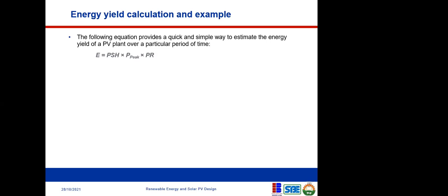That is what this means: how many hours is the sun going to be out? And like I said before, if the sun comes out by 8 and then dies down by 6, it does not mean that the peak sun hours is the time between 8 and 6, which is 10 hours. It does not mean 10 hours. Peak sun hours for us is the number of hours the sun is at 1,000 watts per meter square.